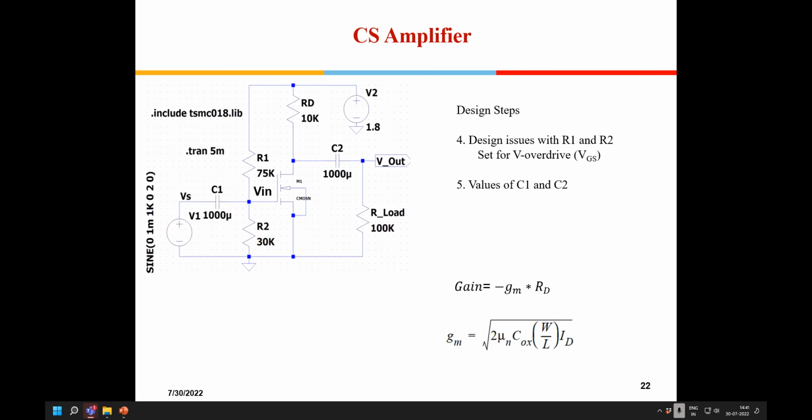Is it okay with all of you? So sir, we have to take care of resistor and capacitor value together. First you decide the value of the resistors, and then you compute the value of the capacitance in such a manner that at least 1 decade lower frequency is the pole which is given by this circuit. Correct. The same holds here also, this capacitance and this resistance, so you need to take care of that aspect.